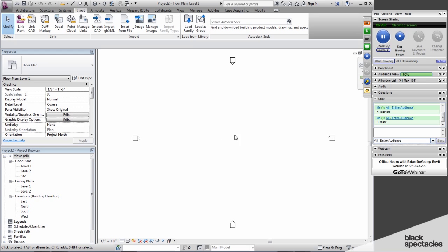If I wanted my building file open so I could edit it, and my documentation file open so I can simultaneously edit some of the documentation, I just open two Revits, one with each file. If I make a change in the building file, I save it, reload it into the doc file, and those changes appear, and vice versa.